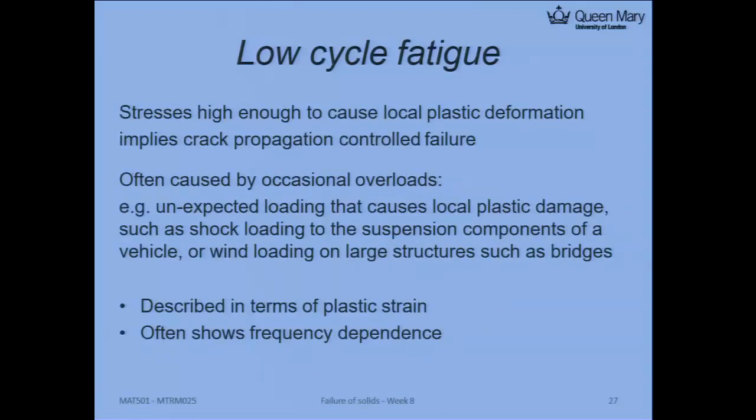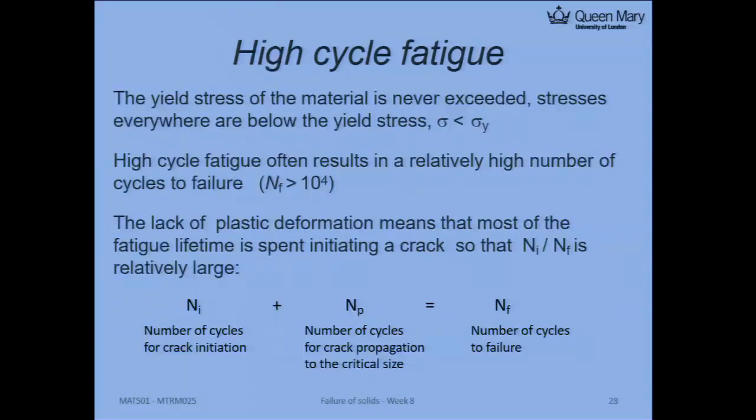People use different measures for that, but I'll give you some examples of low cycle fatigue. For example, shock loading to the suspension, such as a rally car flying and boom, landing on the ground. There's a shock loading, which in a small amount of time generates very high stress. Or some wind load on a large structure, such as a bridge. In this module, we tend to focus on high cycle fatigue, because that's where we can design the material to have a longer fatigue life. And most engineering materials run at stress much below their yield strength. So that's more meaningful to us.